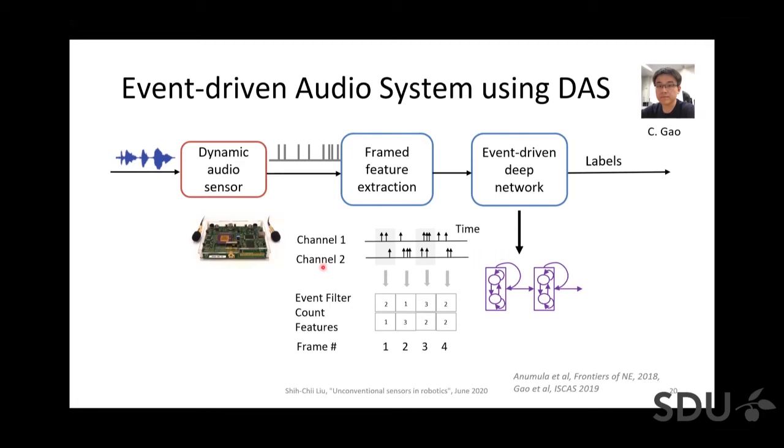So how do we create an input frame? Here's just one example. If I get spikes from 2 different channels, then I can create a constant time bin frame. From the 2 channels, for these 4 frames that I show here, for the first frame I get 2 spikes and then 1 spike in that particular time. Then from here, we get 1 and 3 spikes. Here we get 3 and 2, and 2 and 2. Now we feed these frames into the network as we get the spikes. And if there are no spikes, then you would get 0, 0, and you wouldn't compute the network.